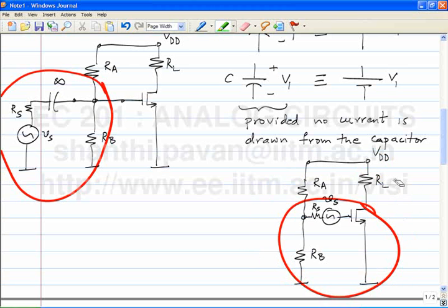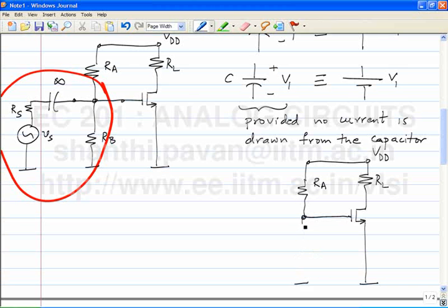Okay, now another suggestion has come about, which is the following. My friend in the last bench says, how about this? Comments on this one? VS will change, yes, because the operating point will change because there is a DC drop through RS. My friend in the last bench will very legally argue that instead of keeping that original RB, I will make it RB minus RS so that the total thing is still RB. And then your objection about the DC operating point changing goes away. Even then there is a practical